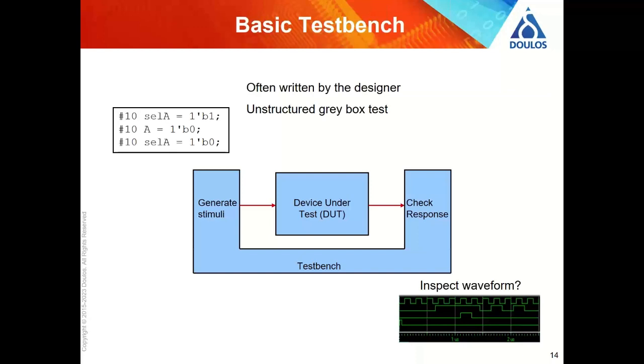To do the test, we need to have some environment to insert our design into. So we've got our design under test, that's what DUT stands for. We can create a test bench, using a language like VHDL or SystemVerilog, for example. And here, for example, we've got our stimulus. Okay, so in this case, we've got some Verilog or SystemVerilog code for the stimulus.